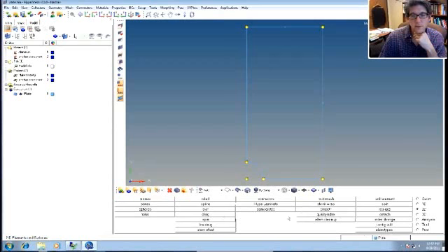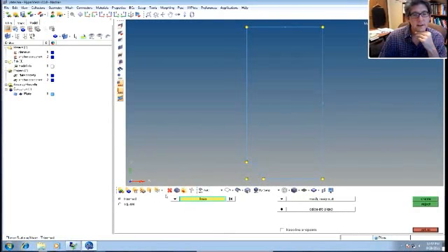There's lots of different ways of doing this stuff. Like if you have a surface, you can do auto mesh. You can do ruled surfaces, spline-bound surfaces. You can do a drag. You can take a line and drag it along a generator curve and make 2D elements. But we're just going to do planes. I use this a lot.